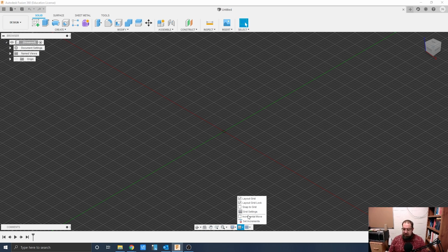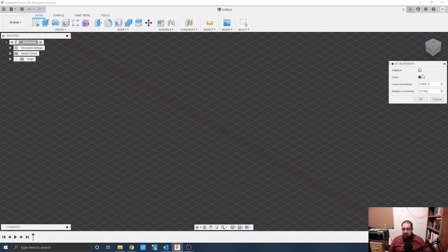Okay, that's going to make it to where instead of doing the whole wide range of numbers in between, it is going to cause it to jump. You'll see right now I have it set to 1/4 of an inch. That's also going to dynamically set based off of what these view when we get into the smallest grid. You can see in there, I used to have it as a 1/4 of an inch. I now have it set to a 1/16 of an inch, which is our architectural based scale, 1/16 of an inch. It's what's on a tape measure. You can change it to a 1/10 of an inch. So you go and change that and go 0.1.